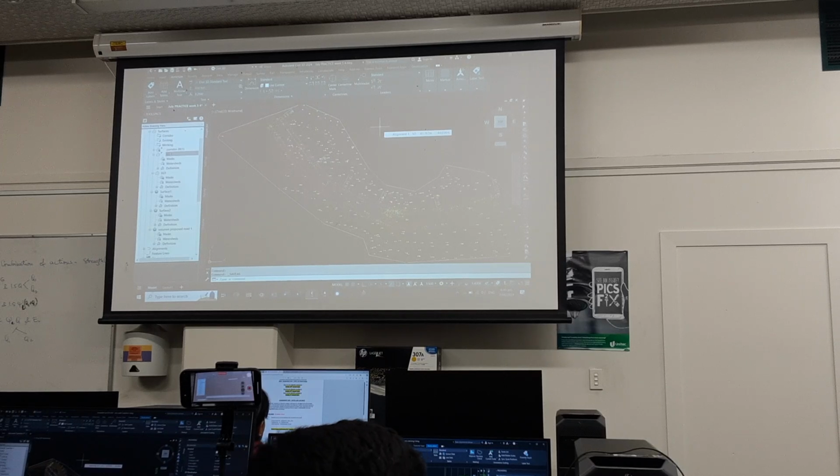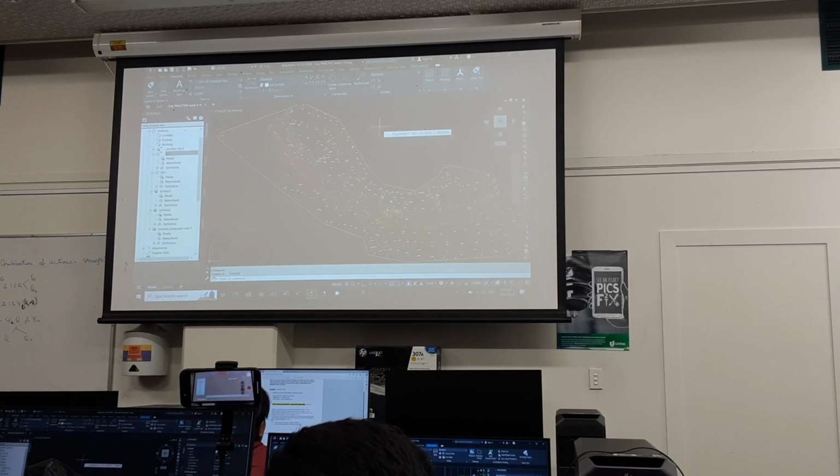We'll soon see. Yeah. So what you might have to do once it goes into AutoCAD is spread it around a wee bit, like put an even number on each drawing, rather than have 2 there and 25 there. You might like to put 10 on that one and 10 on that one or something. And also bear in mind it needs to be in an order. So with the road, you should start from the bottom left at 0, and then 10, 20, 30, 40, then back down the bottom of the page, 50, 60, 70, 80, and then onto the next sheet, bottom left, 90, 100, 110, etc. That's how you do it.